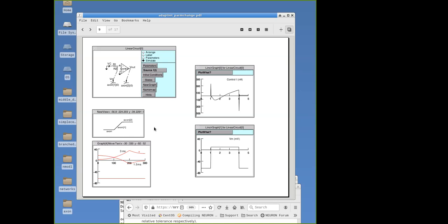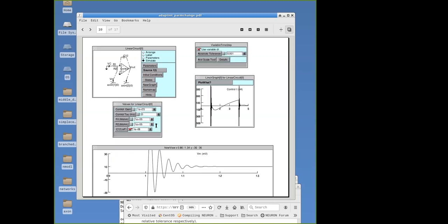What happens if we try to use adaptive integration? Well, with adaptive integration, if we took this capacitor out, we would have oscillations that would completely destroy this figure. Why would we have oscillations that completely destroy this figure? Well, you notice they're extremely fast, okay? They are on the order of 10 to 20 microseconds in duration. And it is a very unstable situation here because of the spatial separation between these 2 points.